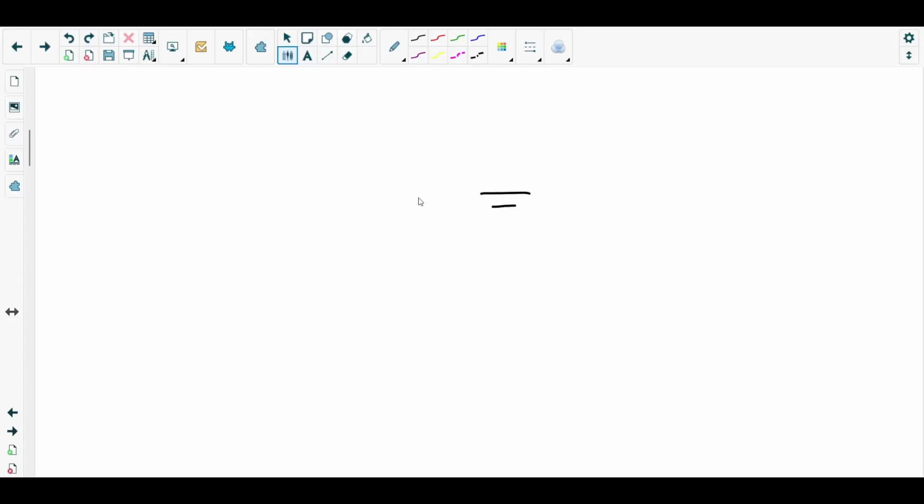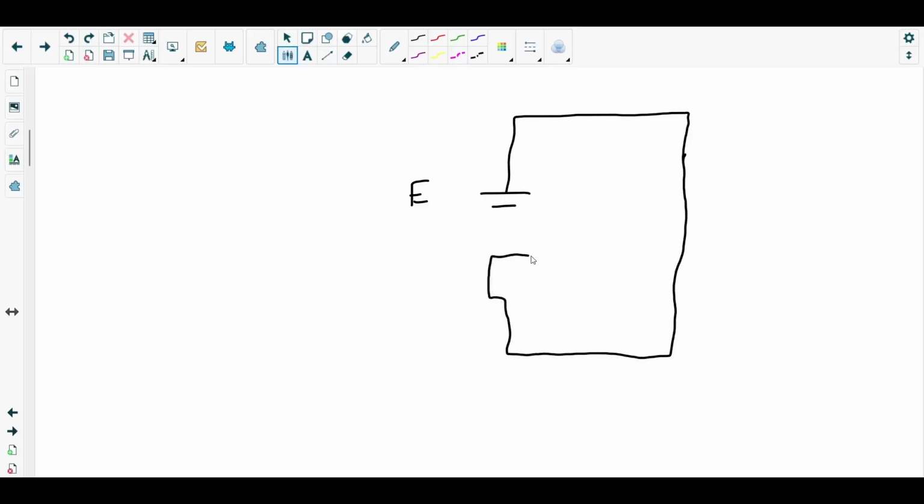So this is the Thevenin's equivalent circuit. I will draw it fast. This is the Thevenin's equivalent circuit, and we short circuited. Look, it's a straight line with no components. Okay, connected in series with the internal resistance r, which is basically RTH, the Thevenin's equivalent resistor.